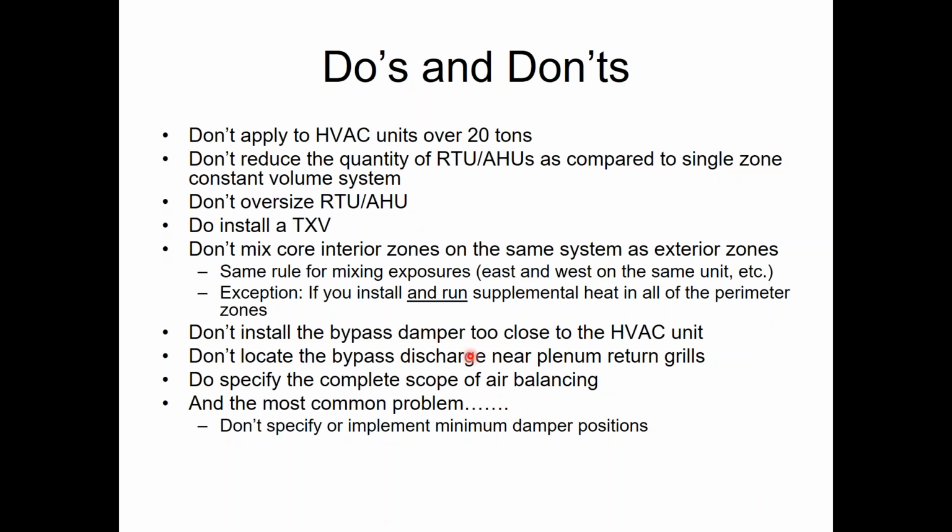Don't reduce the quantity of air handlers you would need because you're putting VVT on. If your job needs 5 rooftops, you put 5 rooftops on and you zone them further with VVT. Do not take it from 5 rooftops down to 2 because you think VVT is going to be some kind of cost saver. It is never a cost saver. It's a comfort desire. It does not save costs. It does not allow you to reduce the amount of rooftops or air handlers.